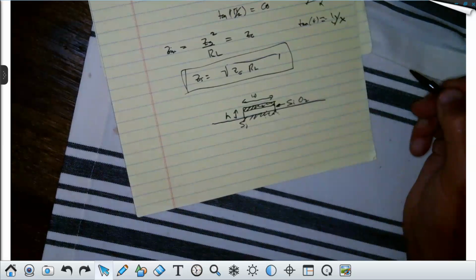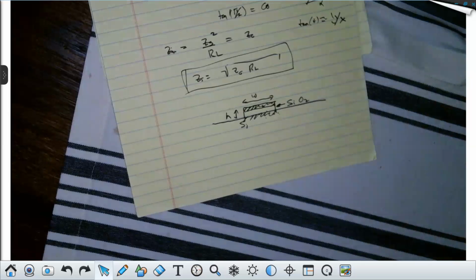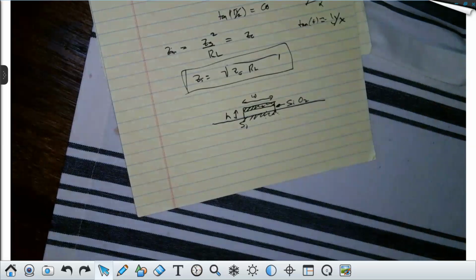Now, quarter wave matching, and this is critical, since the length of that line is a quarter wavelength, only works at one frequency and a small amount of bandwidth. So quarter wave matching does not work for signals that are digital, where you get a spike like this and it goes down. This only works for steady state, something that varies at a constant frequency. Does everybody understand that, class?